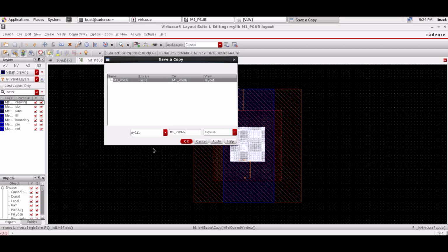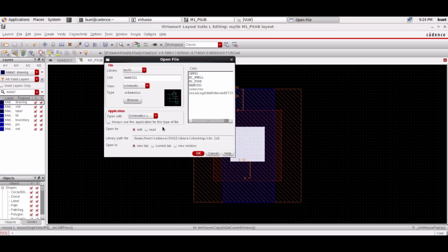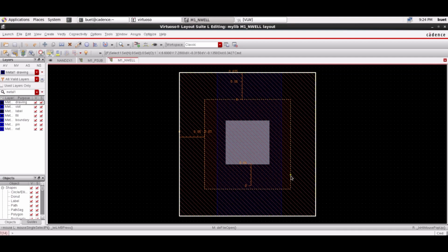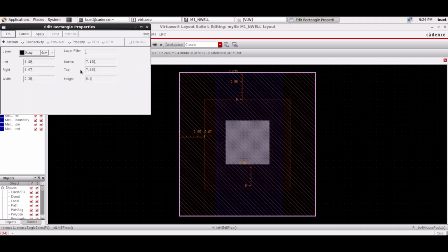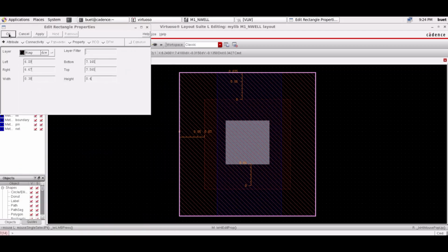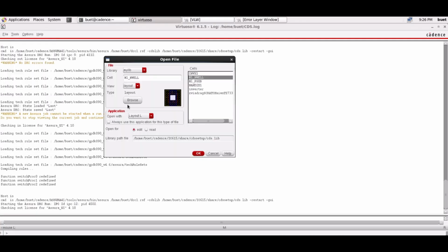Now once I have this p-type, I just need to copy it and change the p imp layer to n imp layer, and everything else remains the same for the n type substrate, and that's it. Now I can use these for each circuit every time I draw the layout for each circuit.